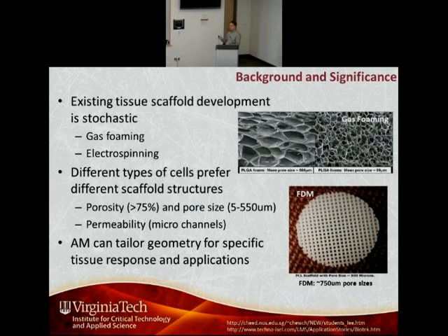So really, what Phil's work, the master student who's been working with me, has been focusing on is making these design decisions: what types of light source, what types of conditioning optics are necessary, what types of DMD to choose from. So you all of a sudden get really knowledgeable about home projection systems. So 1080p, it's not just widescreen TVs, it's 3D printing now. And then, of course, all the focusing optics about how to focus that down, and then getting a linear stage that has exactly the resolution you need, because now we're talking about step sizes on the order of 5 microns per layer thickness.